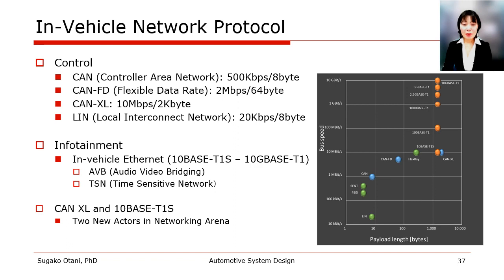In the early 2000s, Ethernet was introduced to the automotive industry for onboard diagnostics and audio-video applications. Applications in the audio-video domain require advanced QoS, quality of service, in the Ethernet endpoints. These requirements are defined in a set of specifications and are known collectively as audio-video bridging (AVB).